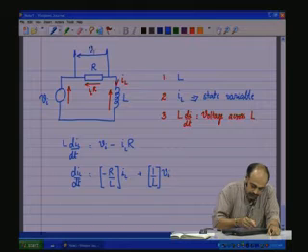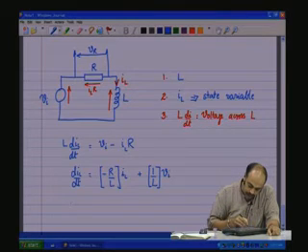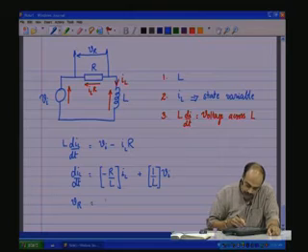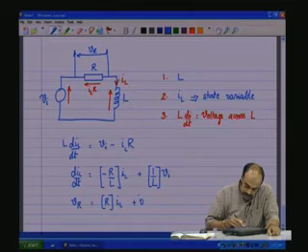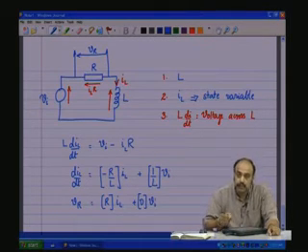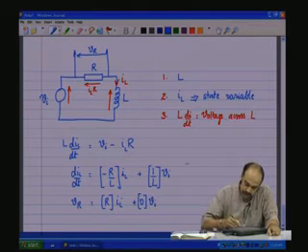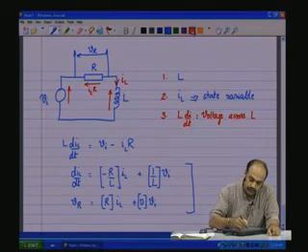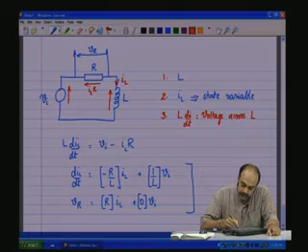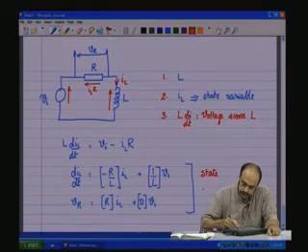So, the output VR is equal to R into IL plus 0 into Vi. So, the C matrix is R in this case. So, these two together fully describe the circuit, and that is the state equation for this circuit.